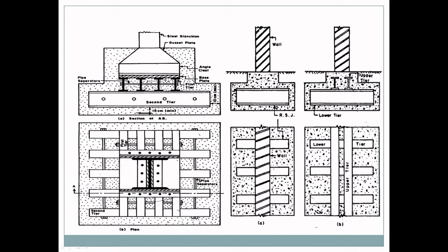Then the grillage beams are placed on this bed at specific distances using separators. The top surface of the grillage beam is kept in a horizontal plane and rich cement grout is filled all around the lower flange of the beam to secure them to the concrete bed. Then the concrete is placed around the beam.